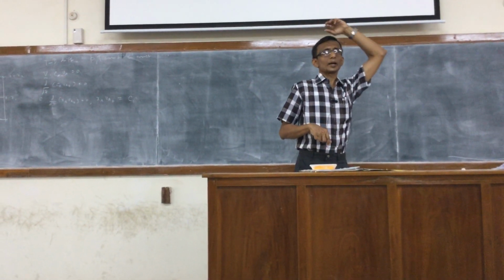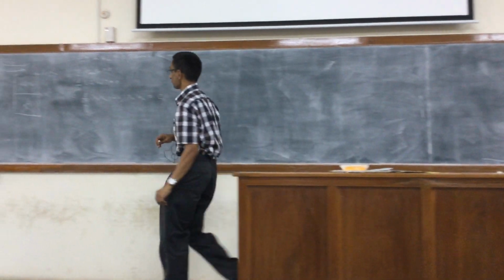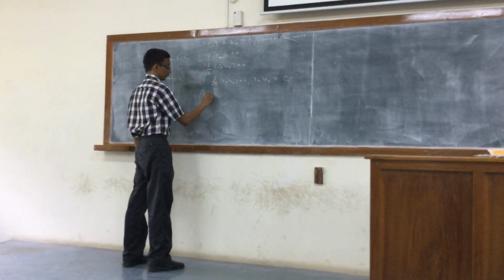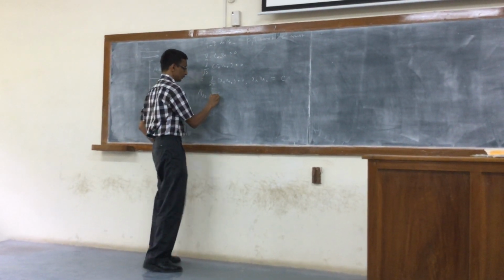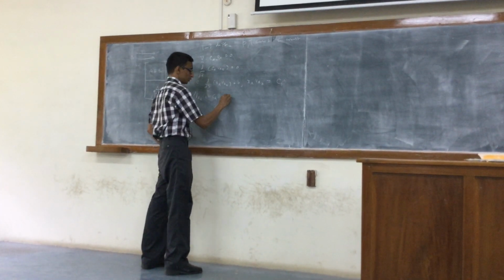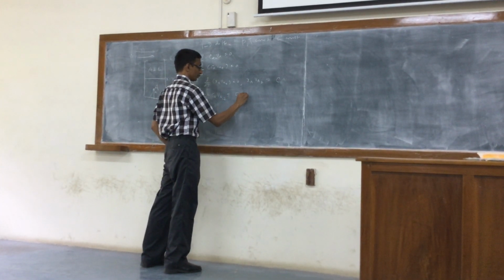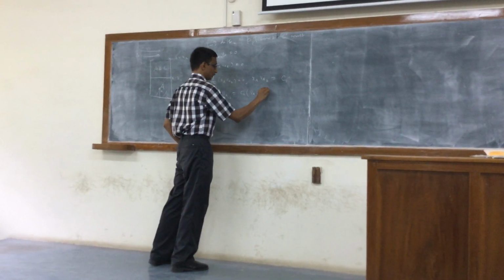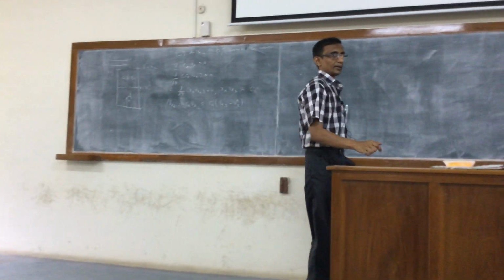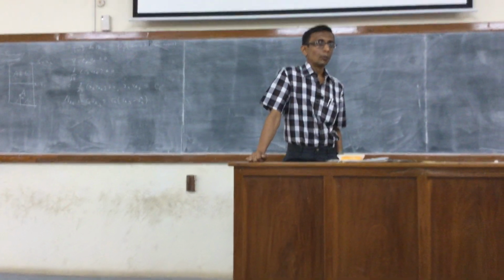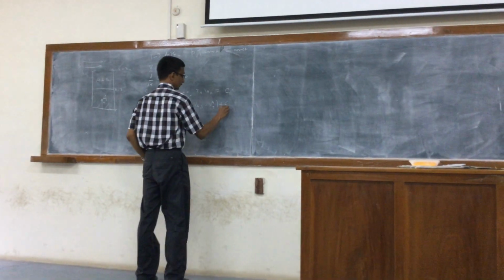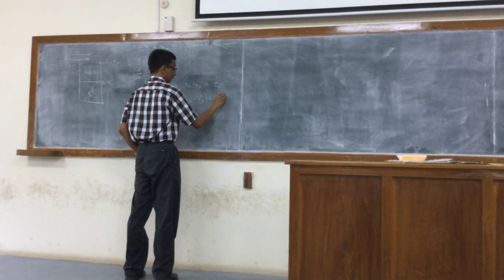The other part comes from writing an expression for N_Az. And N_Az we know is c_A times (v_Az minus v_z star), that is the z component of the molar average velocity, plus c_A v_z star.